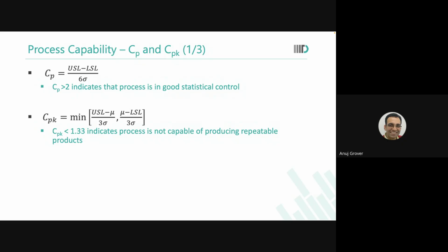When we want to design transistors with a target VT, it may happen that some dosages are up or down, and I finally have my peak of the bell curve not at that target, but a little bit to the left or to the right. So this is one loss of capability.